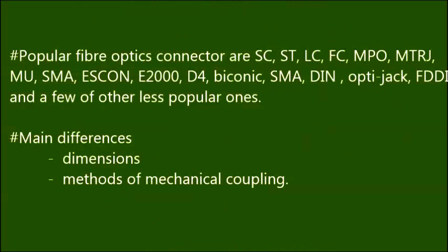There are some common fiber optic connectors used nowadays, such as SC connector, ST connector, LC connector, FC connector, and so on, and a few other less popular. The main differences among the fiber optic connectors are the dimensions and the methods of mechanical coupling.